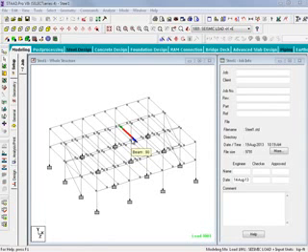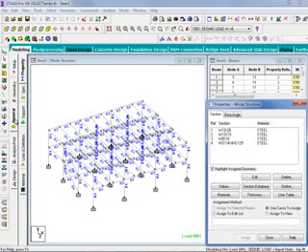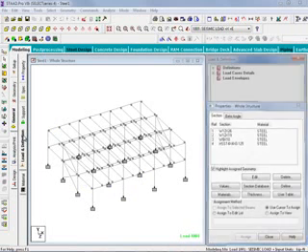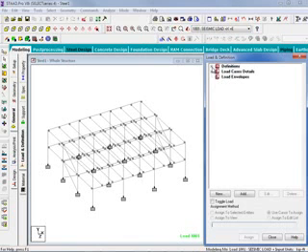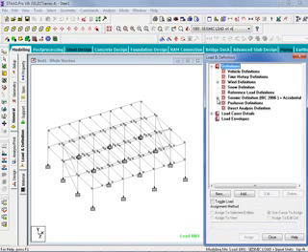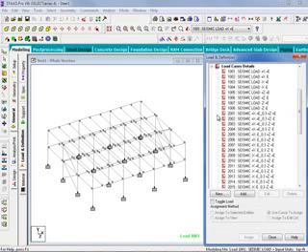To begin applying our seismic load items, we will go to the General tab in the Page Control area and the Load and Definition sub-tab. I will expand the definitions group and we will see that our seismic definition has already been created. And I will also expand our load case details section. We will be focusing on the 1000 series load cases, which are meant to represent the seismic loads in the positive and negative global X and Z axis directions with positive and negative eccentricity effects.